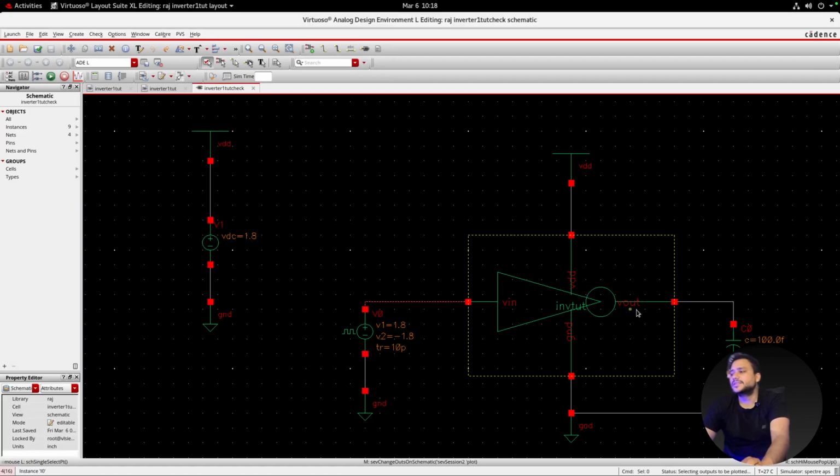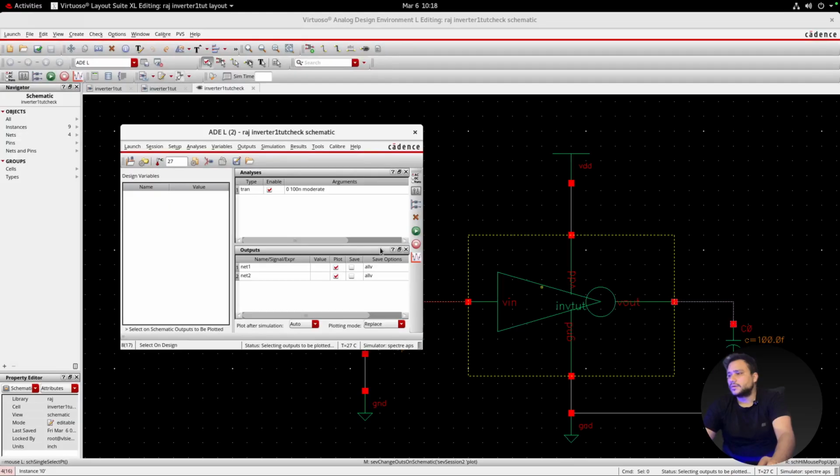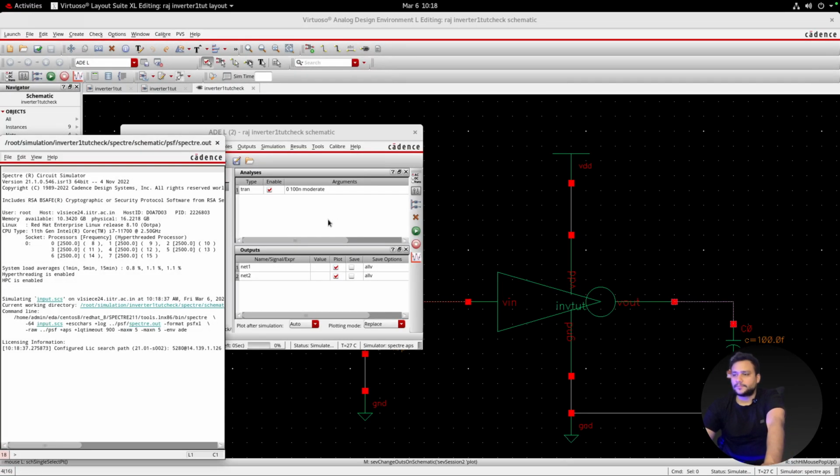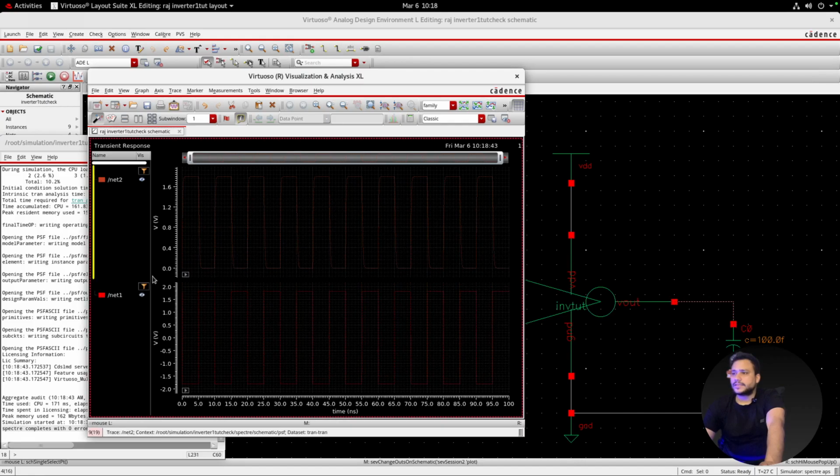These steps are just to show the schematics quickly, and here we are going to run the signal, and we got the output. So you can check. Rising and falling time means the peak to peak value is minus 1.8 to 1.8, and the output we are getting 0 to, it will not be completely 1.8.